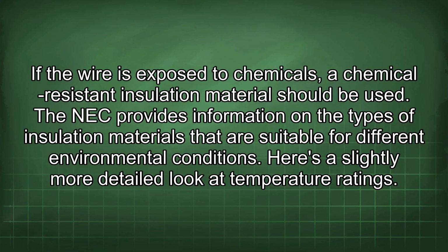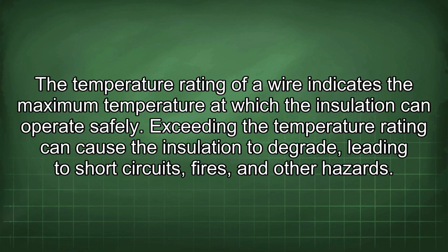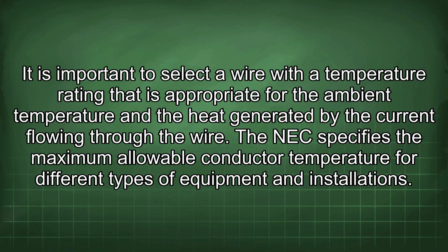Here's a slightly more detailed look at temperature ratings. The temperature rating of a wire indicates the maximum temperature at which the insulation can operate safely. Exceeding the temperature rating can cause the insulation to degrade, leading to short circuits, fires, and other hazards. It is important to select a wire with a temperature rating that is appropriate for the ambient temperature and the heat generated by the current flowing through the wire.